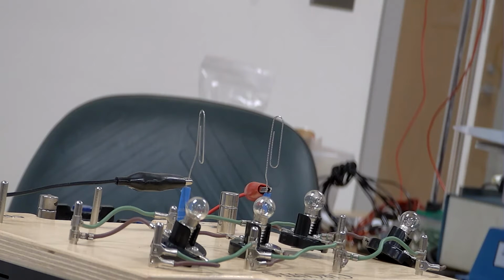What I do, though, is I only scrape off half of it. I only scrape off the coating on half of the wire on each side. So that when the connection is made, it causes the force. But then when it's just about to get to 180 degrees, it encounters the part of the wire that is coated, and so it shuts off the current. And so the kinetic energy of the loop carries it through the next 180 degrees to where it reestablishes the current, and then it continues to rotate. So every 180 degrees, it literally shuts off the current, and then the kinetic energy of the loop carries it through. And then after it goes through another 180 degrees, the current is then reestablished.